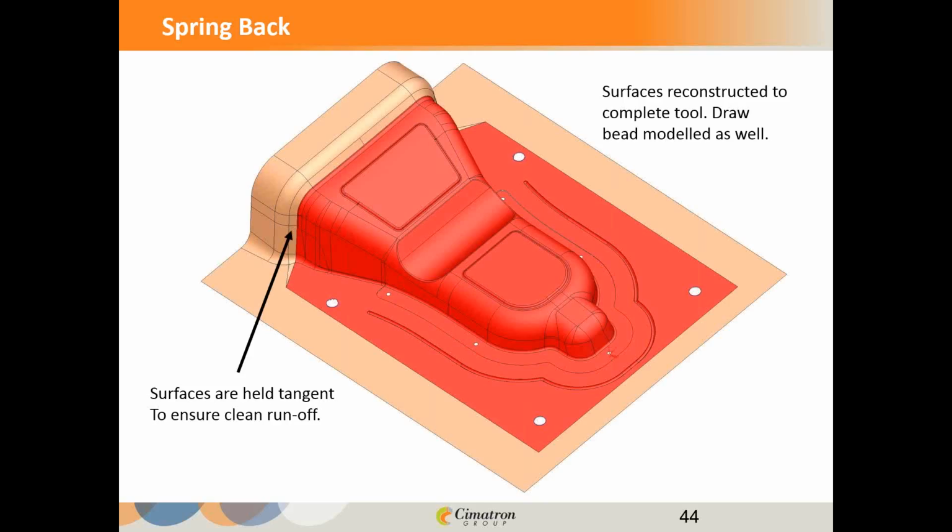If I were concerned about this now and wanted to see, well, I got a 3D model draw bead, let's see how it actually looks, go ahead and run it through the analysis again. The metal's going to act like the metal, and it's going to be constricted by the draw bead, just like you would expect. So we go ahead and run it and not use that predictive draw bead like we did before.